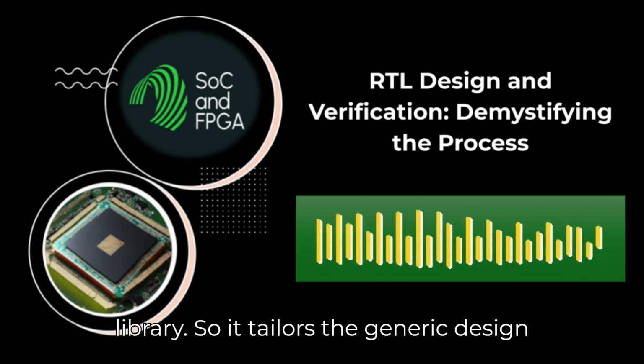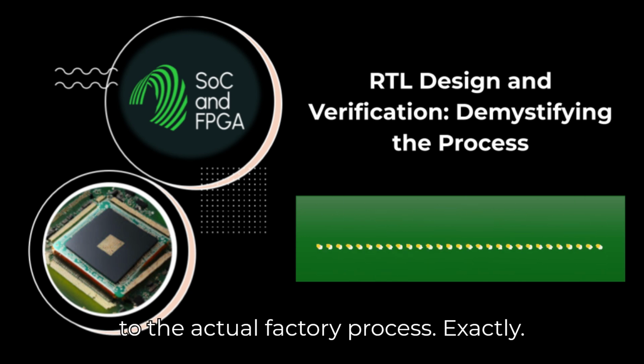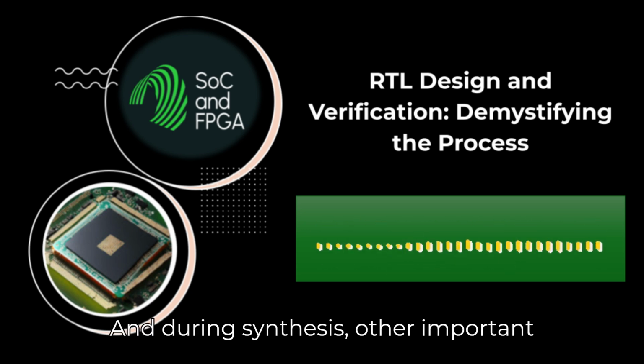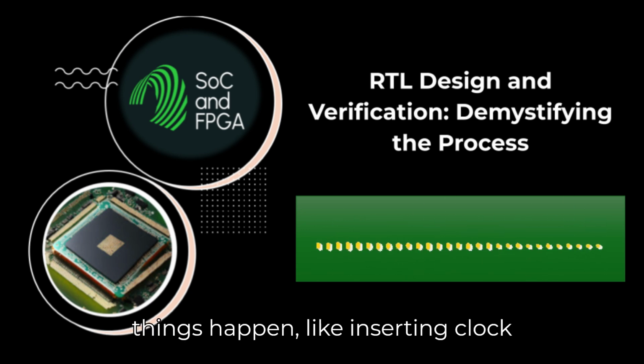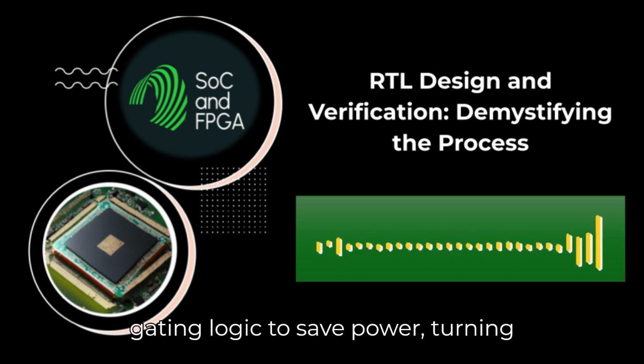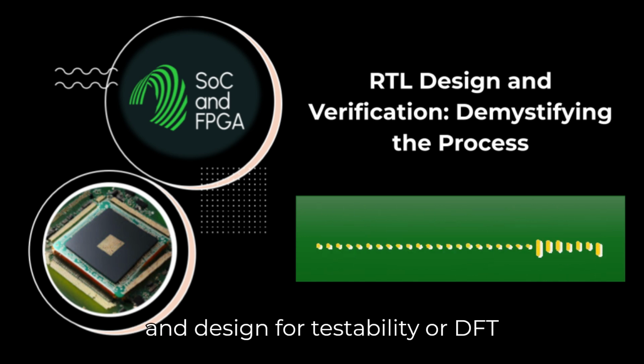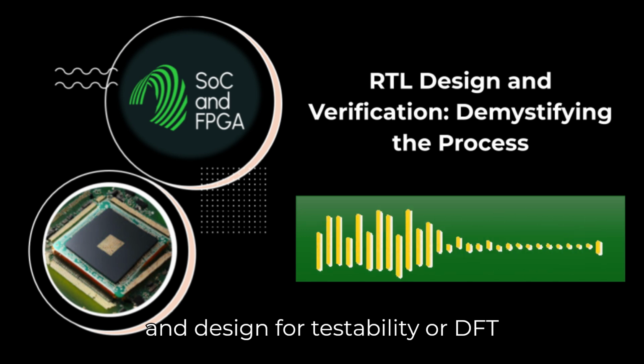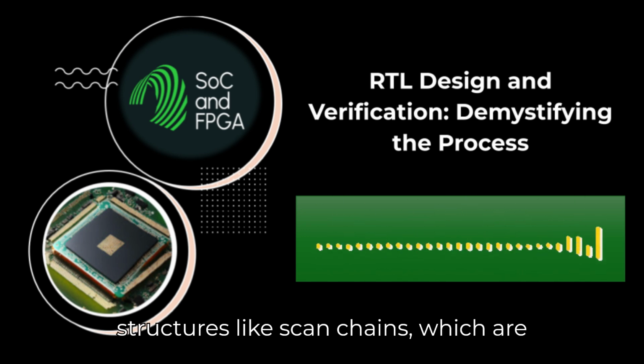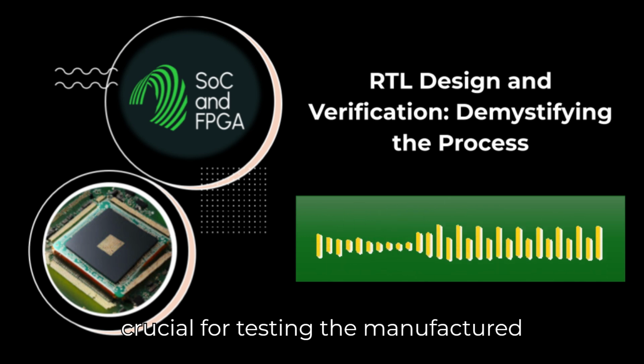So it tailors the generic design to the actual factory process. Exactly. And during synthesis, other important things happen, like inserting clock gating logic to save power. Turning off parts that aren't being used. Yep. And design for testability or DFT structures like scan chains, which are crucial for testing the manufactured chips for